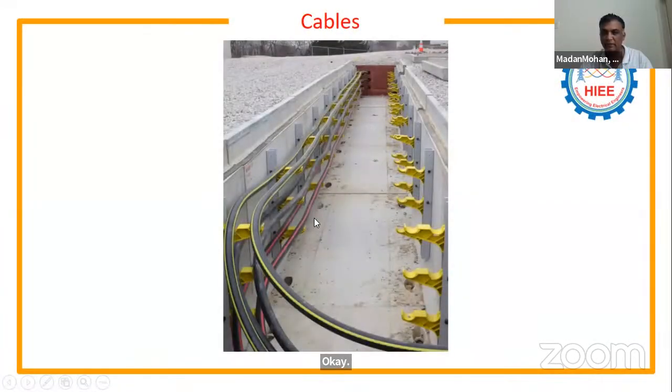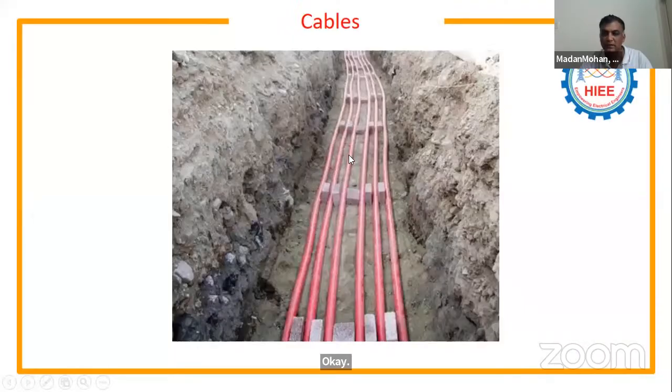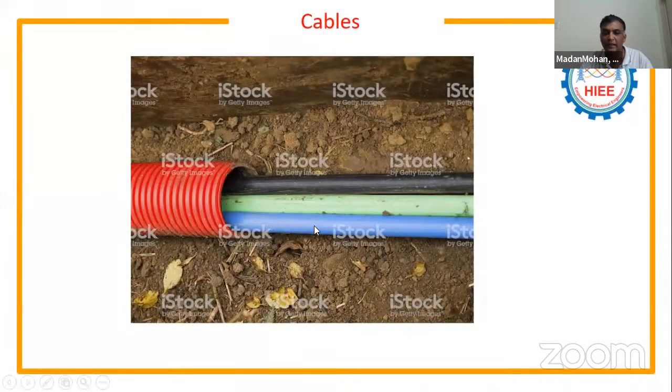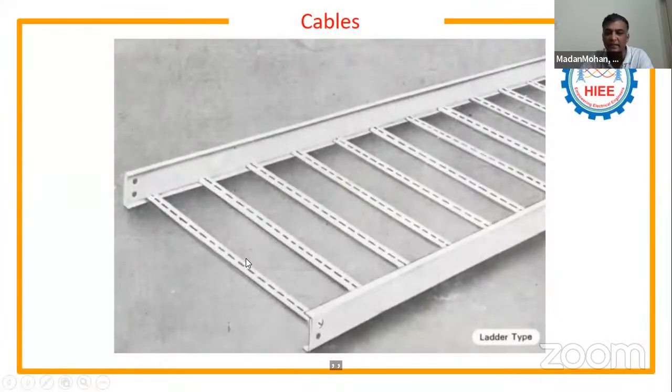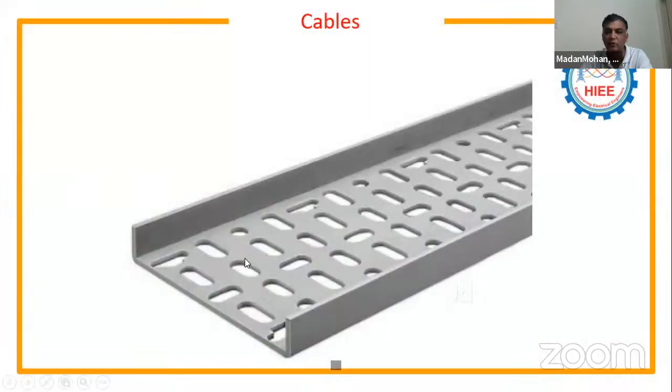This is one way of laying the cables. An underground cable will be laid like this, by maintaining some distance between cables. So this is group rating. And if you are laying the cables through conduit, what happens in the conduit? All the cables are touching each other. This criteria will be different again. So depending upon the different criteria, we select the group rating factor.